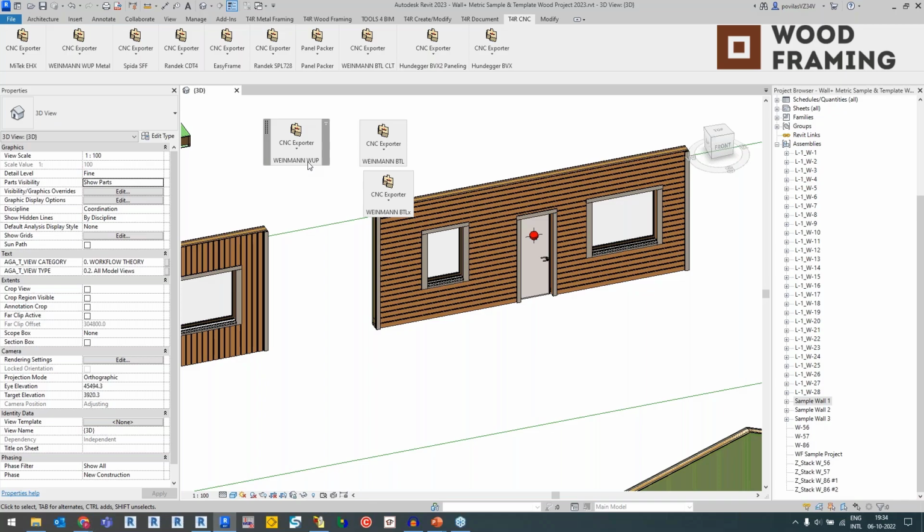So our existing installation can be easily adapted. So walls, floors, and roof framing members, trusses, and separate framing elements can be exported using this application. Usually BTL and BTLx format processing goes for highly detailed and complex beams. BTLx is a newer format whose use is not yet as widespread. Right, so that's BTLx. It's not as widespread, right?